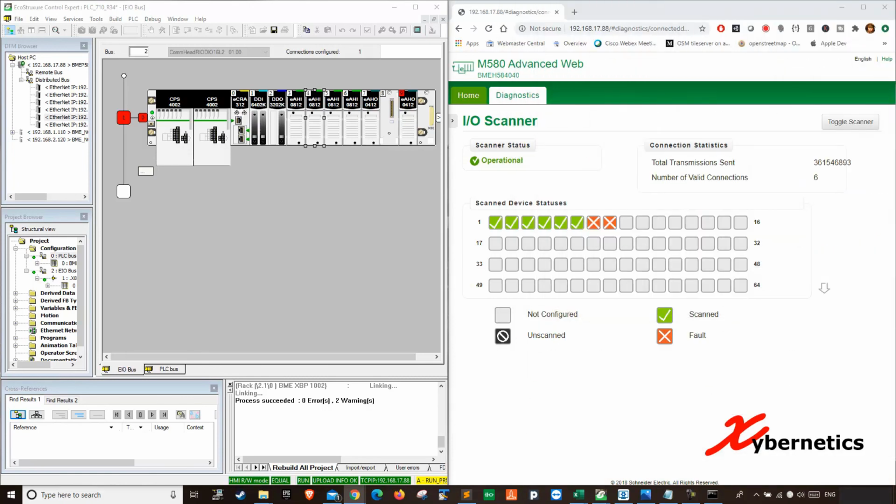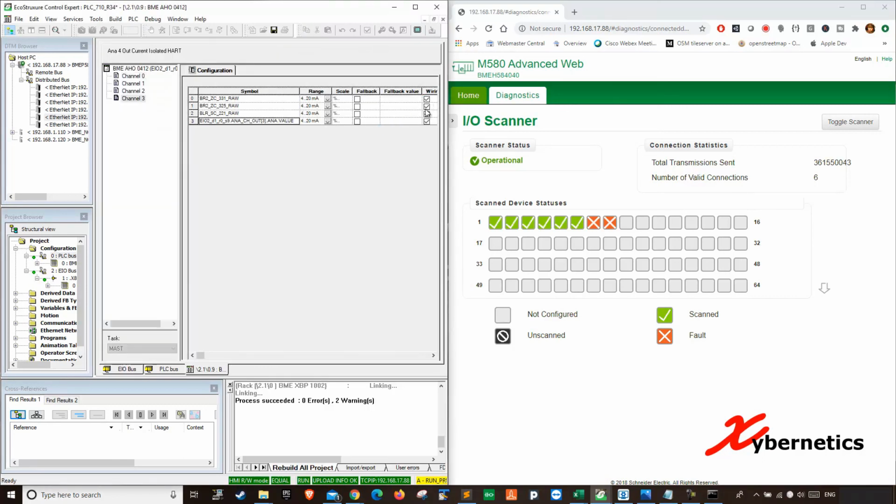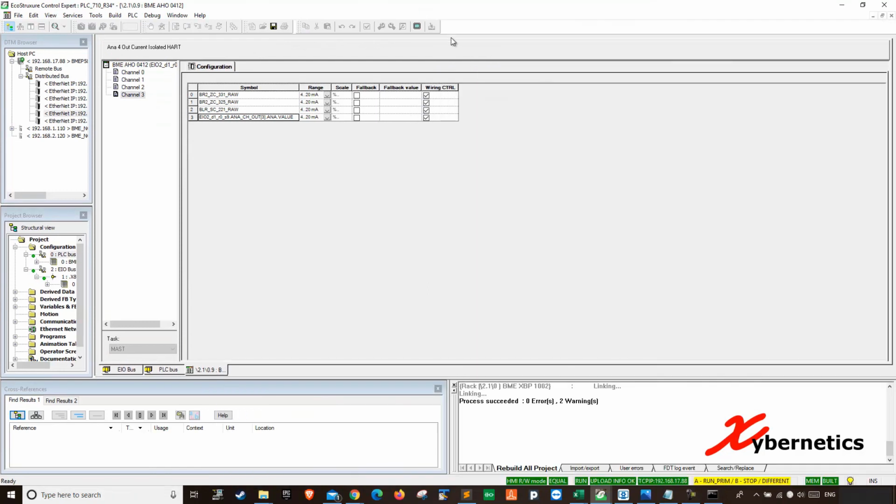And the last thing before I go is that if you don't need this fallback, expand this, if you don't need this guy here, make sure that you remove it, enable it, validate it, and then after that you build it, and then you download it, transfer it to the PLC. I hope this configuration guide will be helpful to you, and hope you won't get stuck like I did for 2 days.